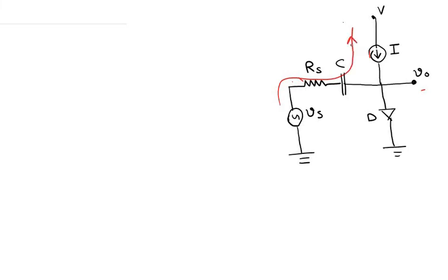It is not allowed for the AC current to flow through this path, because this is a current source which conducts a finite amount of current of DC value I. So it would not allow any extra current to flow through, or any less current to flow through. It always conducts this DC current I. So it will not allow any AC current to flow through it.